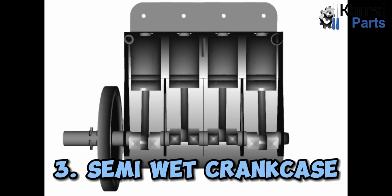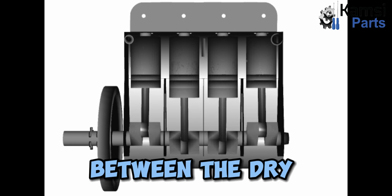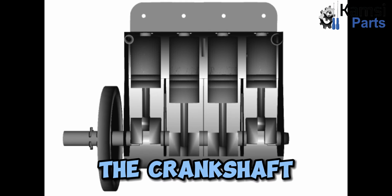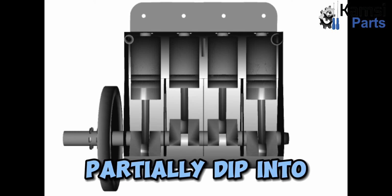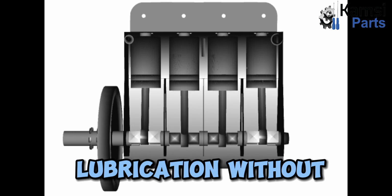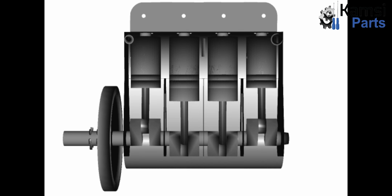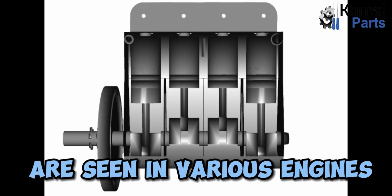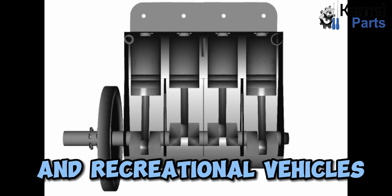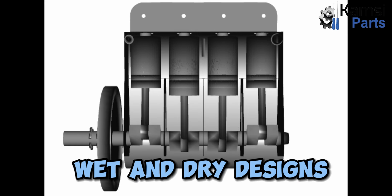3. Semi-wet crankcase. A semi-wet crankcase strikes a balance between the dry and wet designs. In this configuration, the crankshaft and connecting rods partially dip into an oil reservoir, which ensures adequate lubrication without submerging the entire assembly. Semi-wet crankcases are seen in various engines, including some motorcycles and recreational vehicles, offering the benefits of both wet and dry designs.